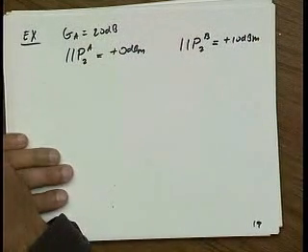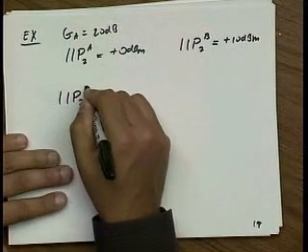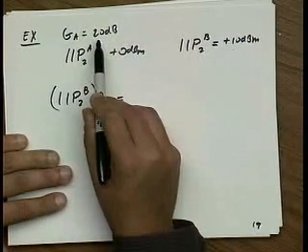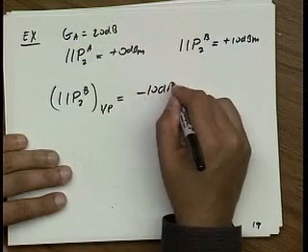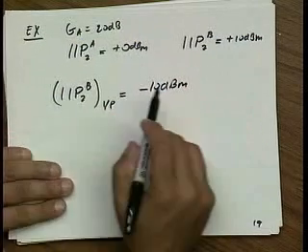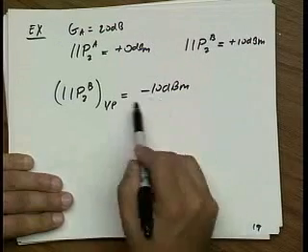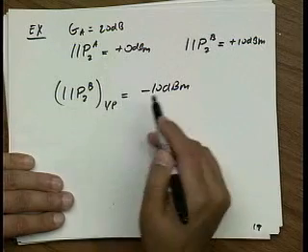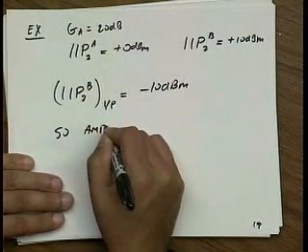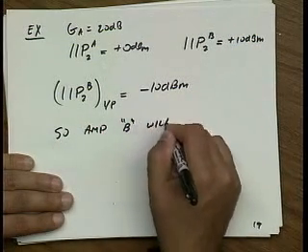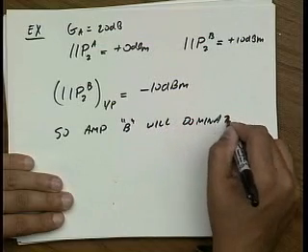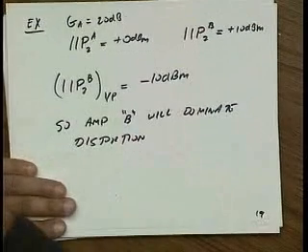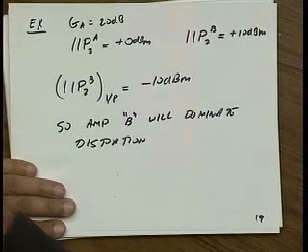Now that sounds pretty good, but if I input refer this, I have to take this gain into account. It becomes minus 10 dBm. So you can see without really doing much math that because the IP2 input referred of this guy is 10 times lower than the IP2 of this point, this will dominate. So amp B will dominate distortion. Okay. Is that clear to everybody?